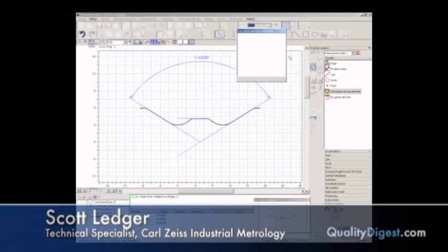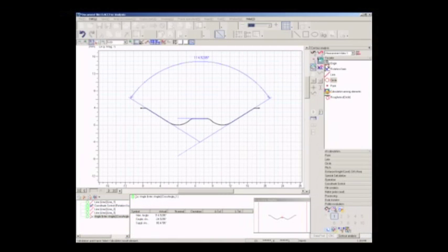Okay, I'm going to continue here and add a couple of circles in these regions. Automatically it drops the radius in, which by the way is customizable. There are a number of things I could report about this radius, including its center position in relation to the origin, or the diameter, or how round that feature is. Those can all be reported also, and that's fully customizable inside the software. I noticed it's pretty easy just to move the annotations anywhere you want, just to lay out this picture. It is, yes.